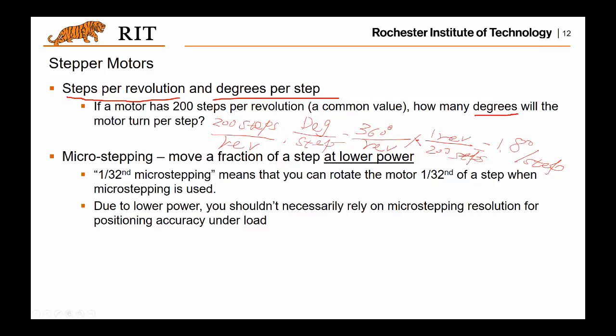Yep. Okay, good. Also for the micro stepping, I skipped the details, but this micro stepping is actually achieved by a lower current or lower power that is in between the two steps. A lower current is given to the motor, and that will make the motor revolve a much smaller angle. That's how this micro stepping is achieved.